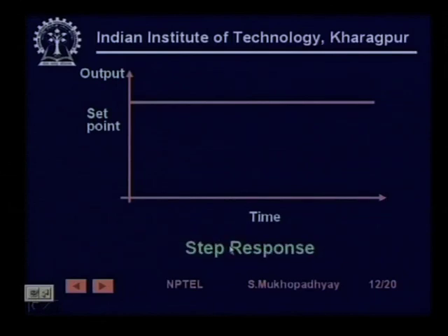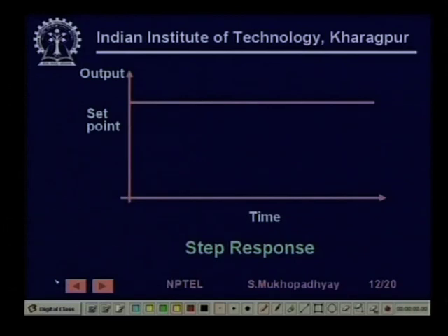The only thing is that this has certain drawbacks too. For example, let us see if we give a step response, how does the loop work? Suppose the process starts from here, and as you have given, there is a lot of error. So the proportional controller now generates a positive input which drives the plant. So the plant goes up and we are likely to get a step response like this.